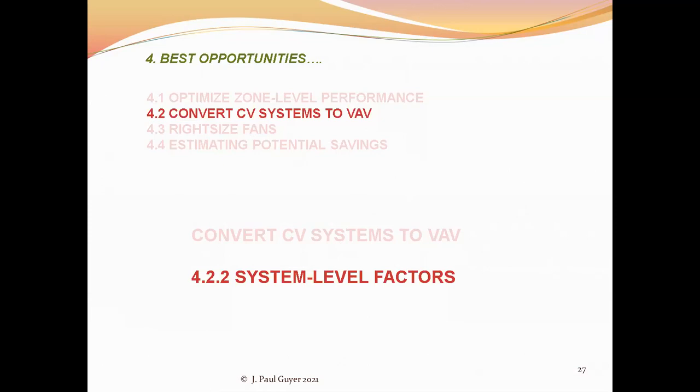For a dual duct or multi-zone system that you're replacing, see whether the existing hot and cold dampers are controlled by one or two actuators. Converting these systems to VAV usually requires two actuators so that the hot and cold air supply can be regulated independently. Having two actuators already installed usually leads to a simpler, less expensive conversion. And it's possible to add a second actuator if there is only one, but it will add cost and complexity to the project.